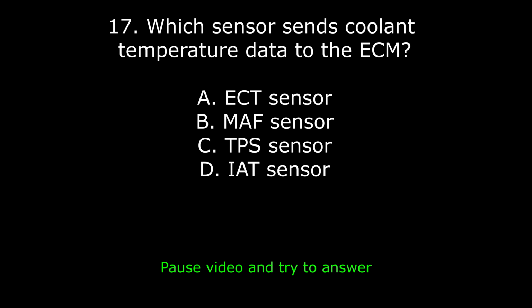35. The AC compressor clutch does not engage. Which step should be done first? A. Check clutch coil resistance and power supply. B. Replace the compressor. C. Recharge refrigerant. D. Disconnect the battery. Answer: A. Check clutch coil resistance and power supply. Explanation: verify voltage and ground at clutch before replacing components.